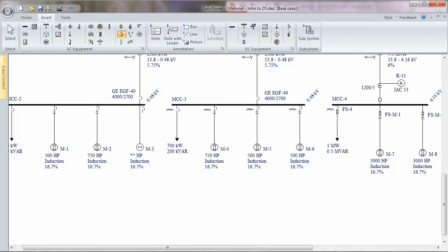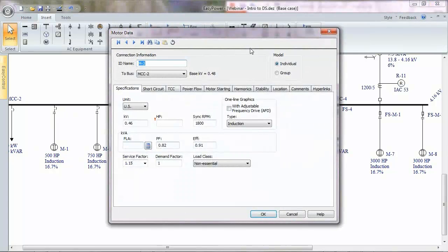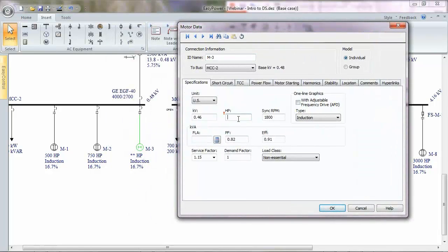And I'm going to add a low voltage breaker. I'm going to make it just like this 500 horsepower, so I'm going to give it the same exact breaker contactor. Now I do admit a 500 horsepower motor on 480 volts is pretty not realistic. I know, okay, just bear with me. These are examples. More than likely you're not going to get over 250, 300 horsepower. I know that, so 750 is almost a very unrealistic thing, but let's assume we have a 500 horsepower motor, and I'm just going to type that number in.